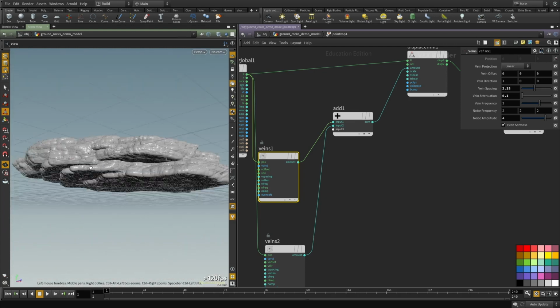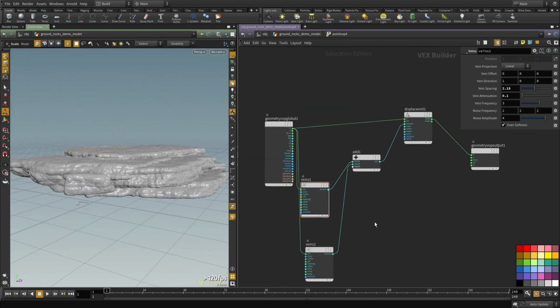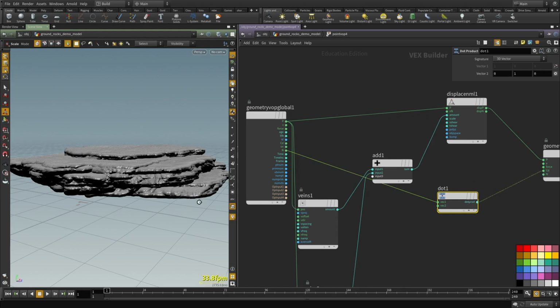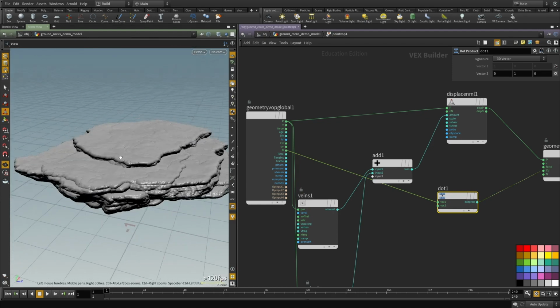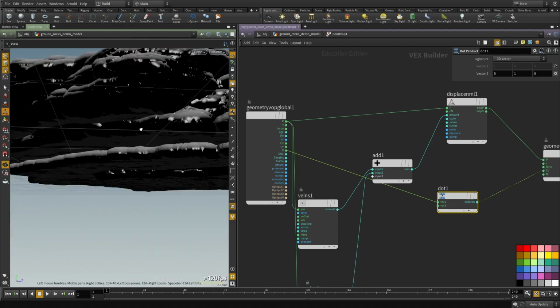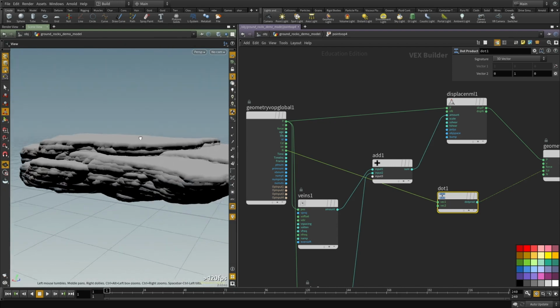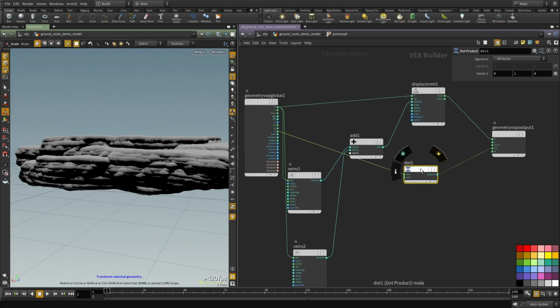And then we're going to create a mask to remove all of this. So how can we isolate that? Well, we can take the normals and do a dot product, and that should create the mask for us that we need. Okay, cool. So you can see everything that is facing upward is now colored with white, and everything that is not is colored with black.